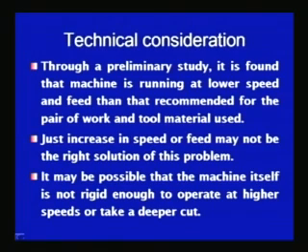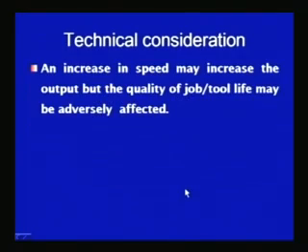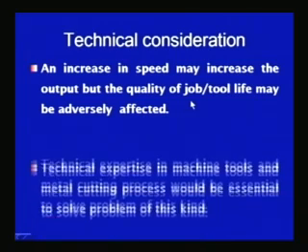So, this kind of possibility can only be explored by the machine tool expert. It may be possible that the machine itself is not ready enough to operate at higher speeds and to take deeper cuts. It would be important to look into that an increase in speed and feed may also lead to poor quality of the job and reduced tool life.